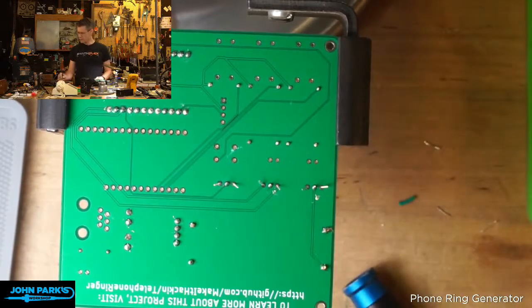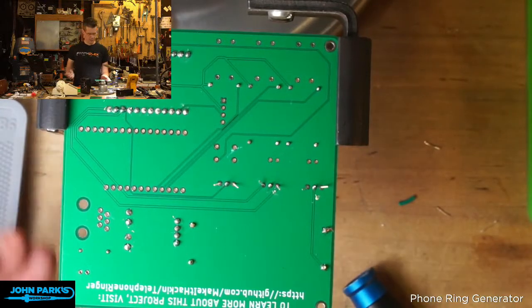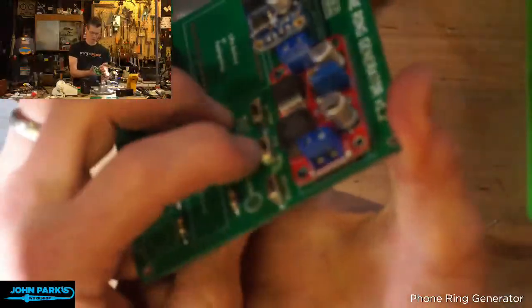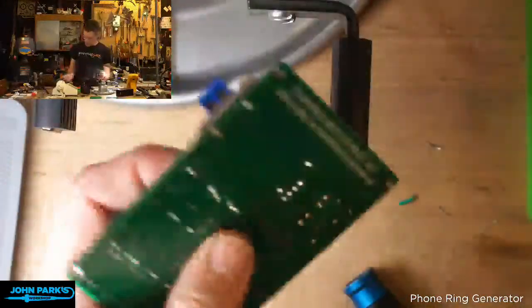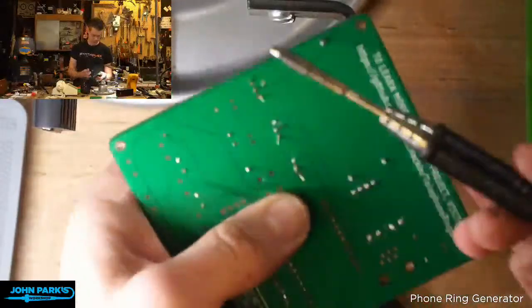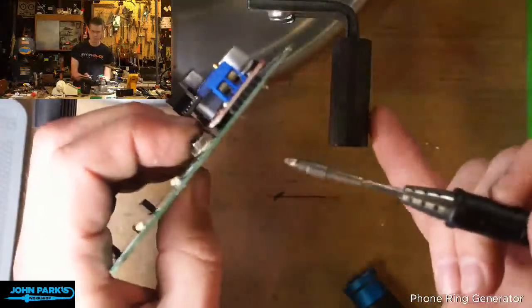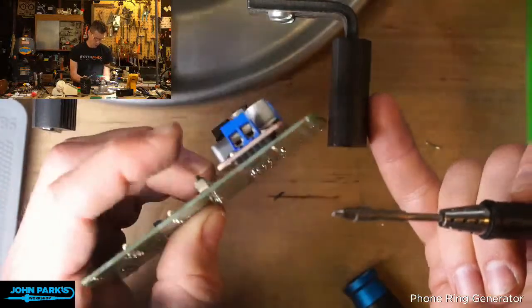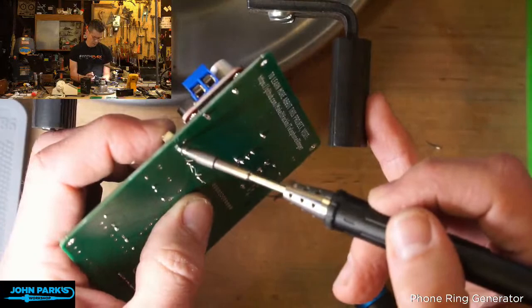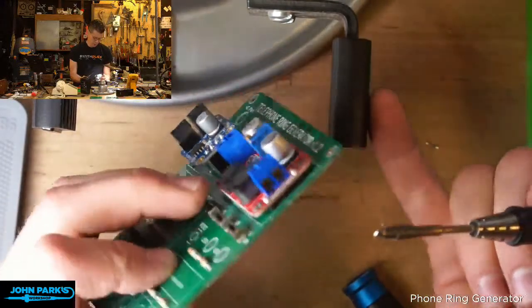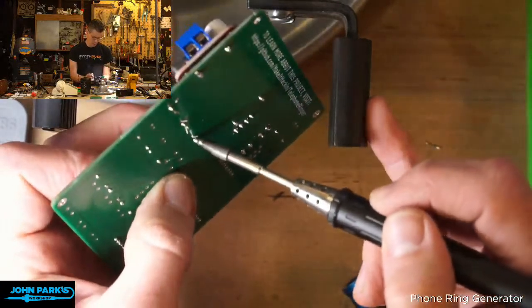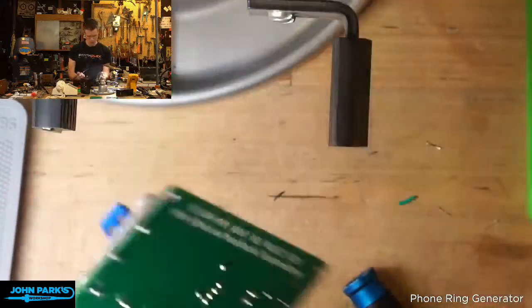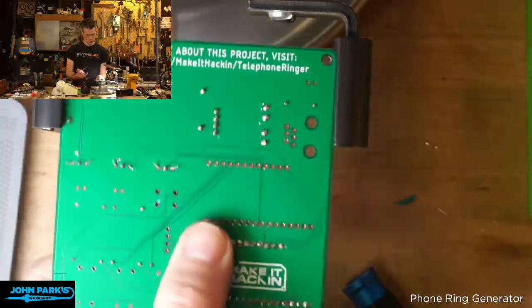Okay, so with one leg soldered, it's a good idea to flip it over and check. This one's a little janky, so I'm going to just heat that and work that into place. You can see here, I'll heat it and then get it flush. It's best to do this when you just have one leg of something soldered. Okay, those look neat. I like it. So now I'll flip it over and finish.